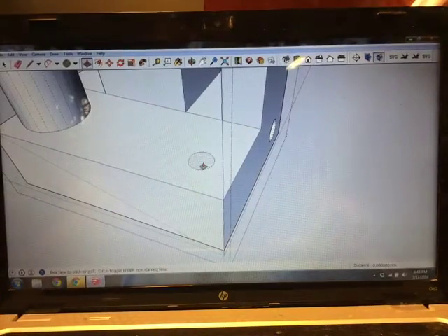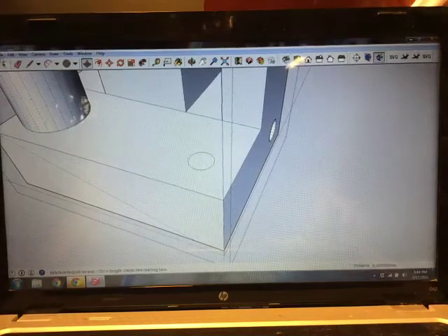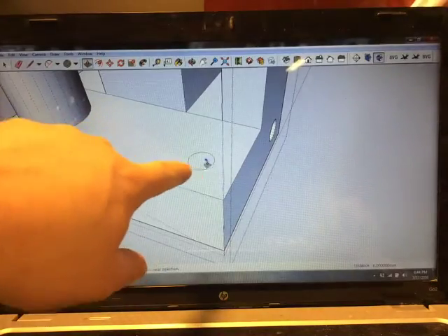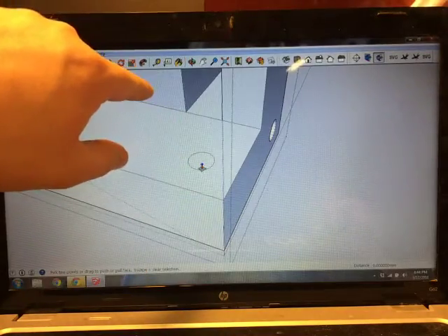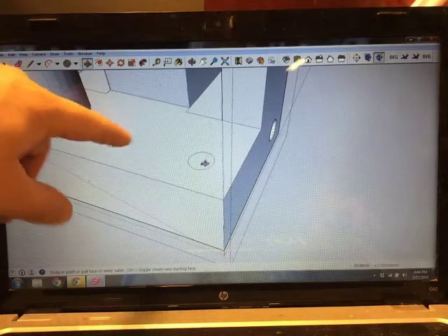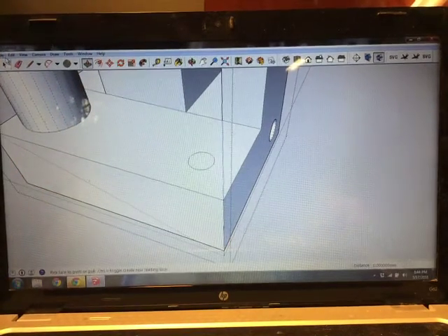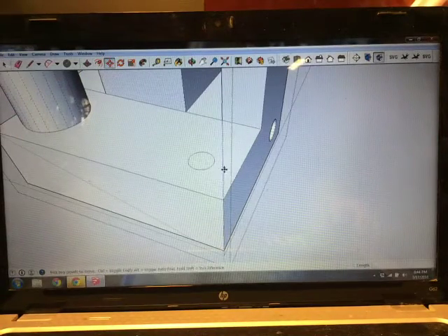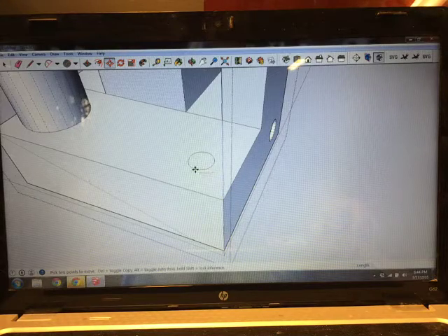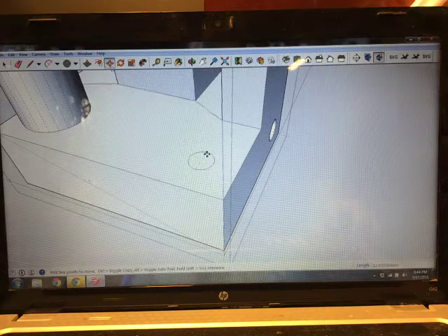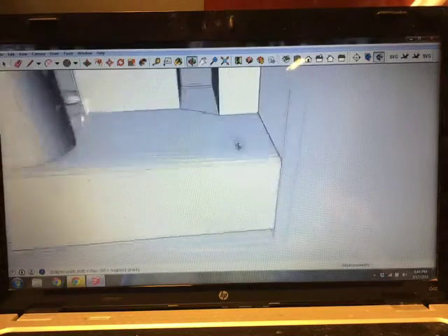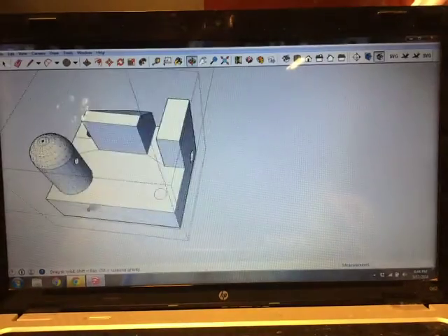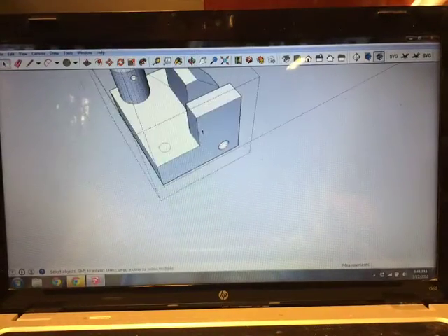I should probably also, oh yeah, that was something interesting. If you have a surface selected and you go to extrude and you're like, how come it won't let me select the face? Because it's thinking that you're going for this face. So if you try to click that, it's going to move that one. But that could be a nice feature, because let's say you want to extrude this surface a certain distance back. You don't know what that distance is, but you know it has to be the width of this hole. Then you can select on one edge of the hole and select on the other. So there are things that you can translate width relationships across to other components.